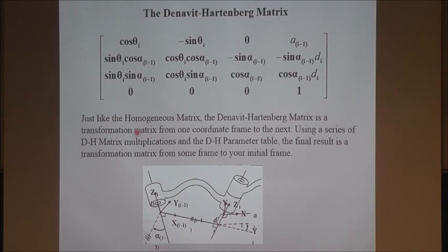And for example, when I give you a configuration of a robot, or if you go to the toolbox and print, let's say, Puma 560, it gives you the homogeneous transformation, and it gives you the table, showing you which of those parameters are changing, which ones are not. In a Puma robot, you have 6 coordinates, 6 angles, all 6 of them are changing, are moving. Just remember how you do it yourself.